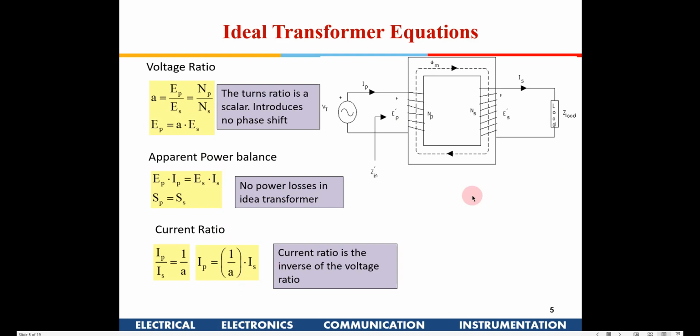And now physically, let's try and understand what happens in a transformer. Suppose I have given some voltage out here. There is a coil out here that creates a magnetic field, right? And the secondary is open. As long as the secondary is open, this magnetic flux creates an opposite voltage in the primary coil itself, so that no current will flow here.